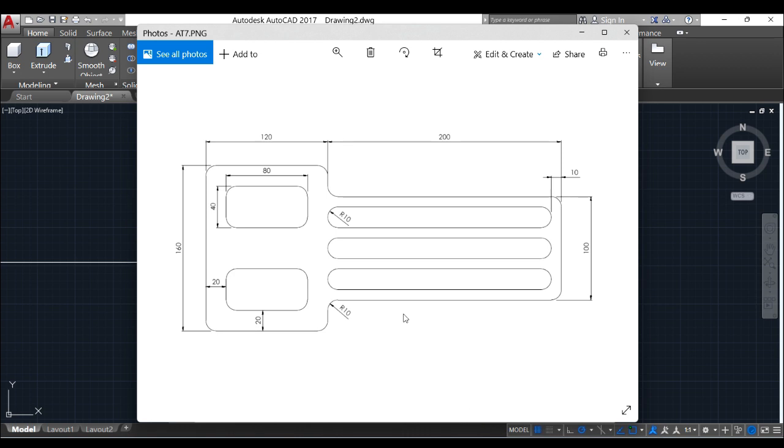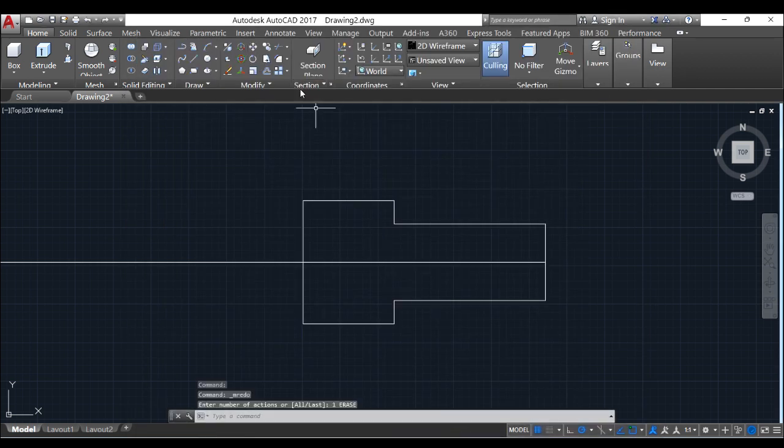So if you look at this, there is a distance of 20 millimeters in from this left hand side before these designs were started, and there's also 20 millimeters up from the base before the design was started, and the design is basically 40 by 80 in dimension. So I'm going to offset 20, 20 and then start. So we can see now we will select offset